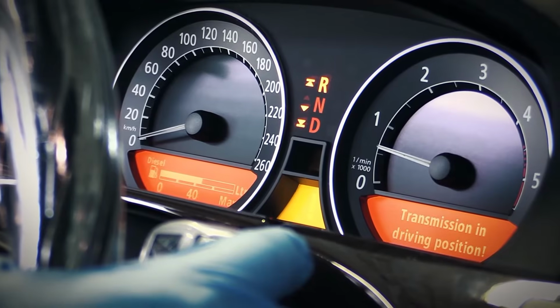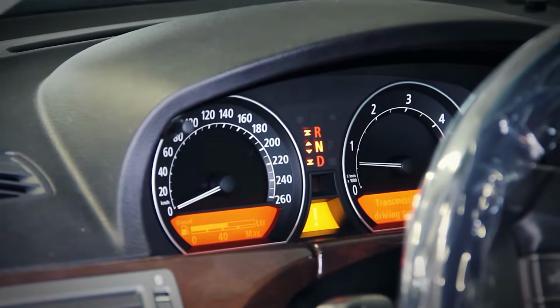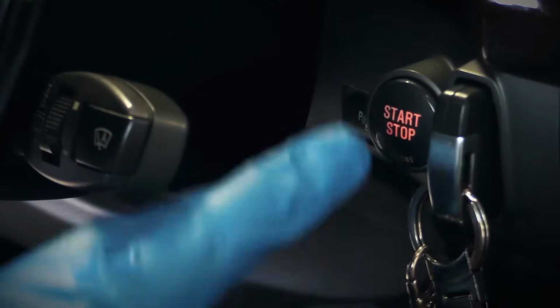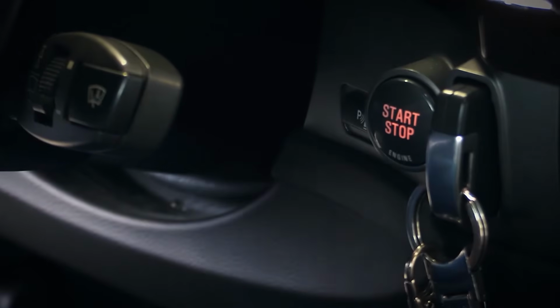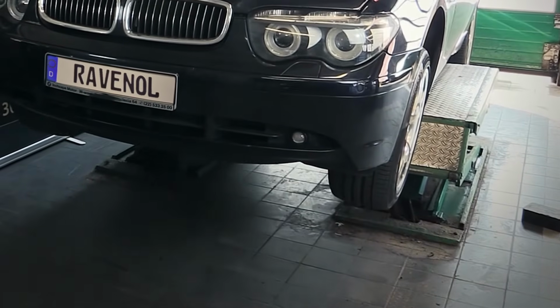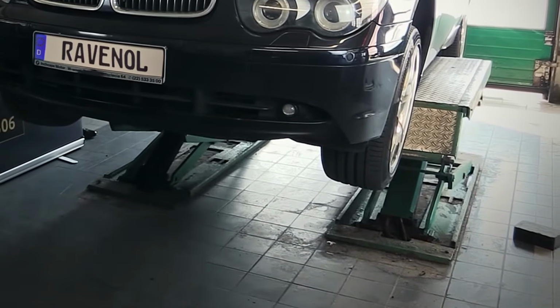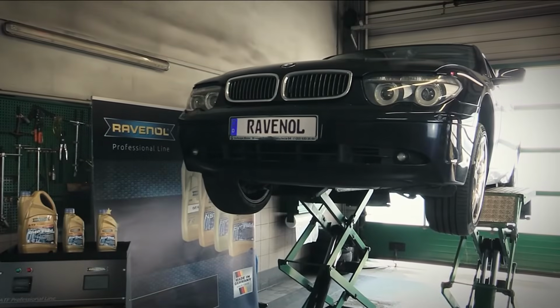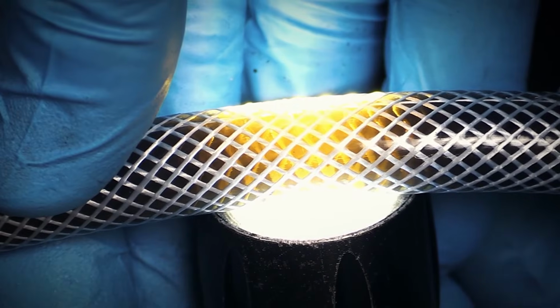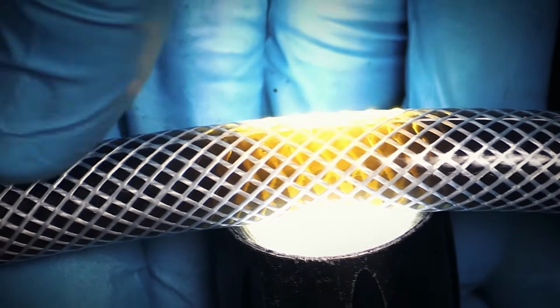The device will stop automatically if the direction of flow has not been selected correctly. As soon as the preset quantity of oil has been fed in, the ATF Professional Line device will automatically end the dynamic oil change process. The ATF Professional Line is designed in such a way that it is not necessary to flush out the device's lines, and there is also no risk that clean oil will be mixed in with old oil in the filter system.